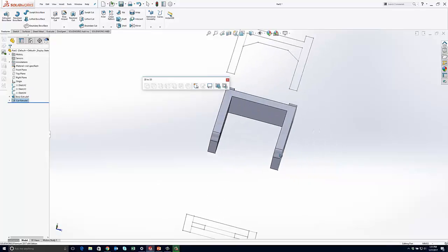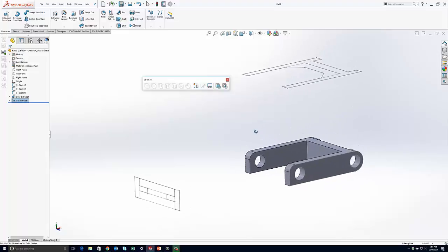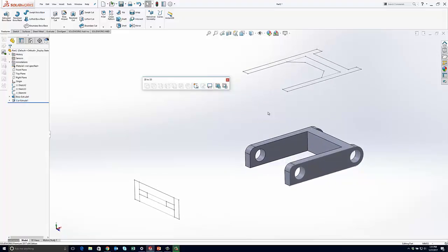So we can see we're starting to shape up here and have a part that is looking like our 2D views had shown us here. Now the last thing that we want to create with this part is our rib. So once again, I'm going to use my select chain to grab a couple different sets of geometry here. And I'm also going to control select. So I just hold down control, do the same thing when I'm picking my multiple chains.